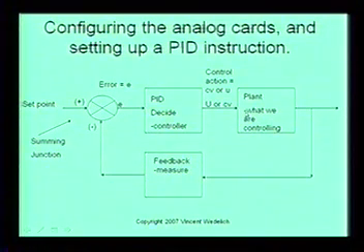It fills the tank. Let's say if this is a control valve or something like that, it actually starts opening up the control valve if the tank needs to fill, or closing the control valve if the tank needs to empty. And then you've got closed loop feedback here, and this is measuring the tank level in this example. It comes back here and it says, okay, now I'm 0.5. So it says this is a 1 and this is a 0.5, so we have an error of 0.5. So again, the PID decides and makes a change, and decides how fast to make a change.